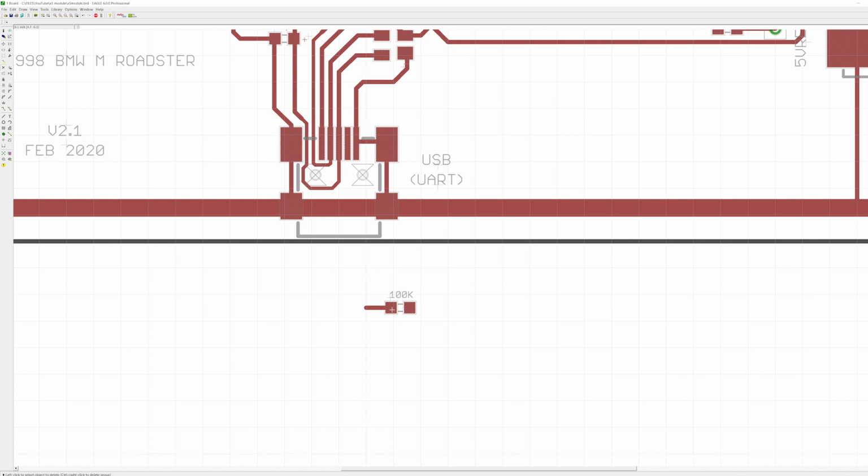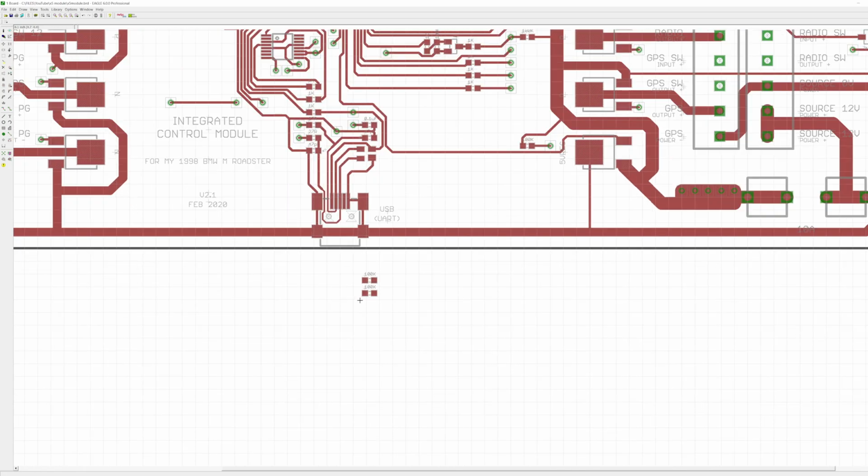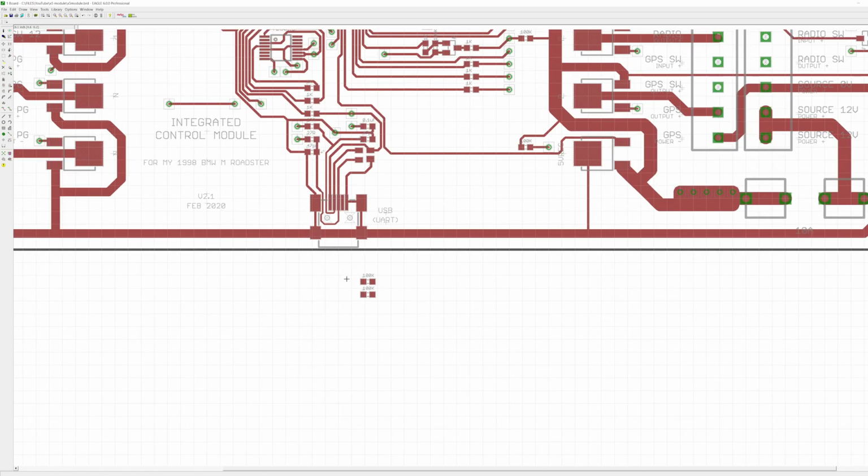Let me just delete that real quick and then delete that. So if I select this, right click, copy group, I can drop this at any interval of 0.1 inches and it should be exactly in line. And so that helps me keep things symmetrical. It helps me keep things spaced out in an appropriate way. So that's an overview of how I actually use the tool.